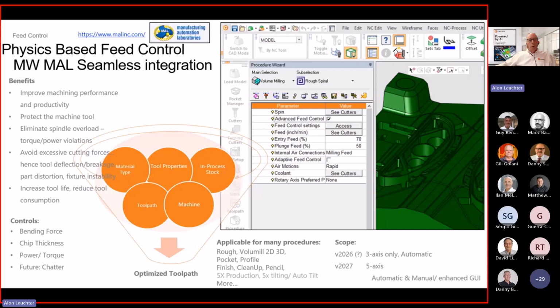So we actually are agnostic with which input goes into the feed control. It's just a toolpath that, okay, we wrap all the data and send it behind the scenes to the engine. Feed control applies the calculation and sends the toolpath back to Cimatron as a standard Cimatron toolpath. You can then navigate, post-process, simulate, seamless as any standard Cimatron toolpath.